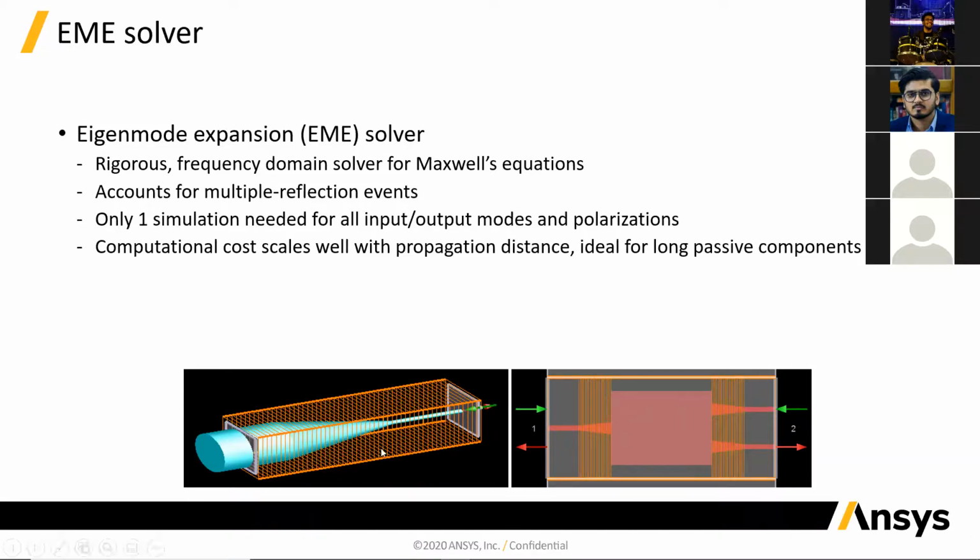So the nice thing about it is that once you have defined your geometry and all the cross sections, you first just calculate the supported modes in all of the cross sections once, and then it's all post-processing, figuring out how the overlap works from one slice to another, and how light is going to propagate from one end to the other. Then you can change the distance between those cross sections and optimize your design without running any further simulations.